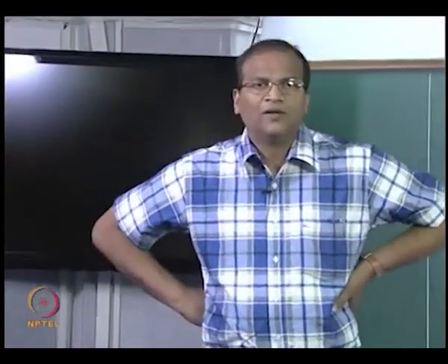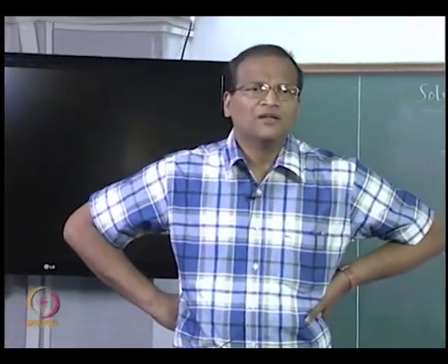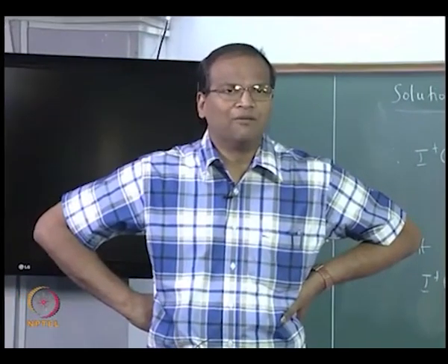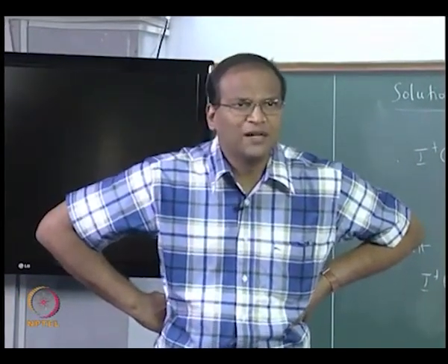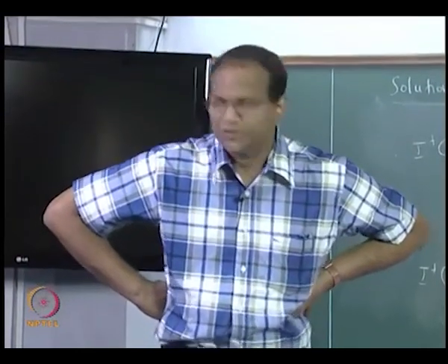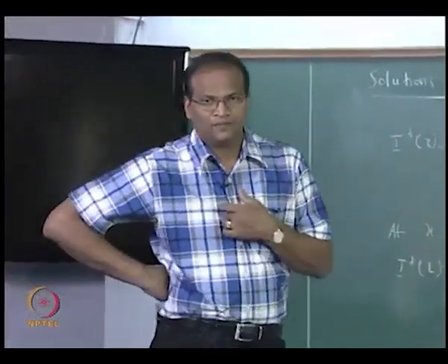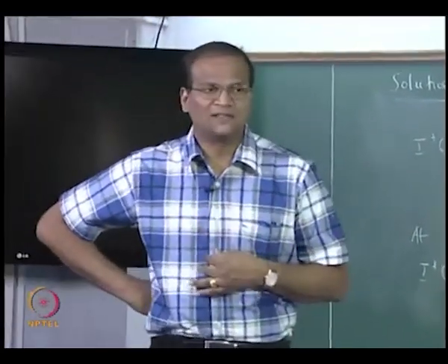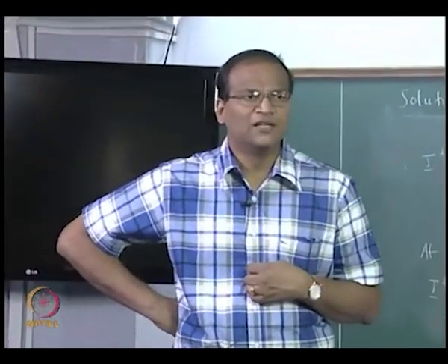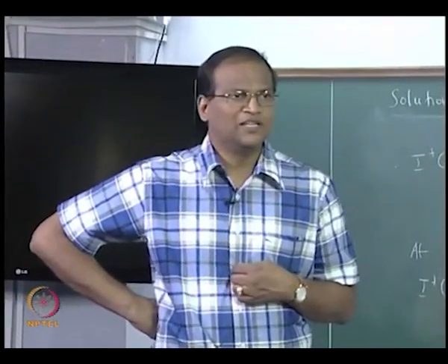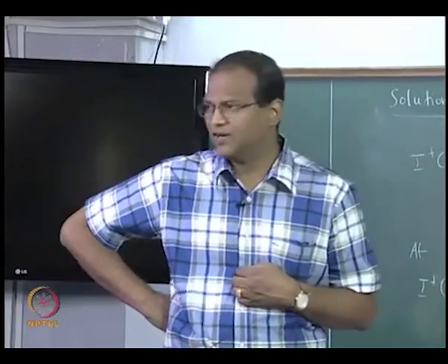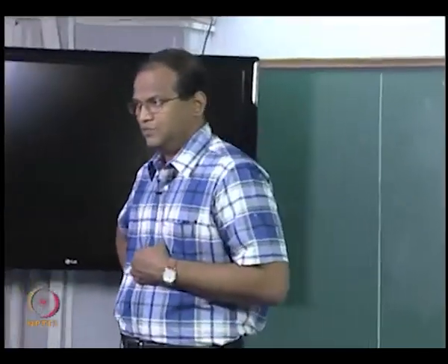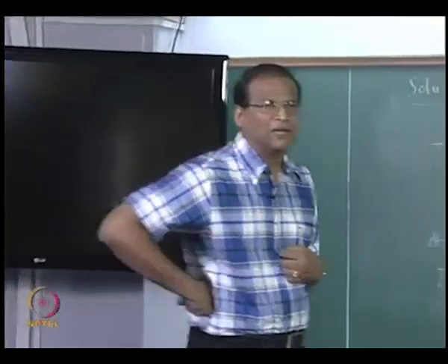So if for two media the optical depth of one medium is higher compared to the other, what does it mean? Its capacity to absorb radiation is much more, correct. An optically thin gas is one in which tau is very small, that means it absorbs minimum. An optically thick gas is something which has got a terrific tau, little will emerge out of an optically thick gas.